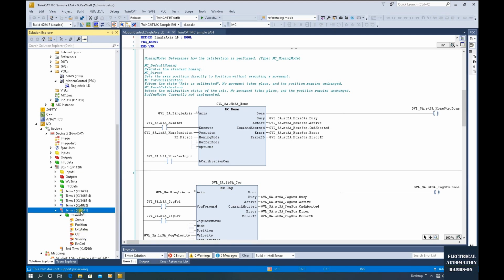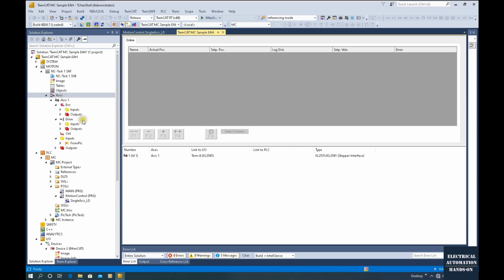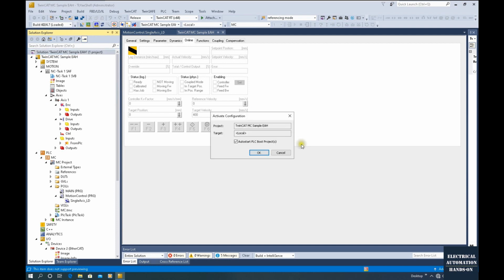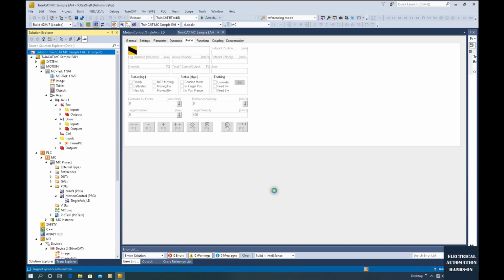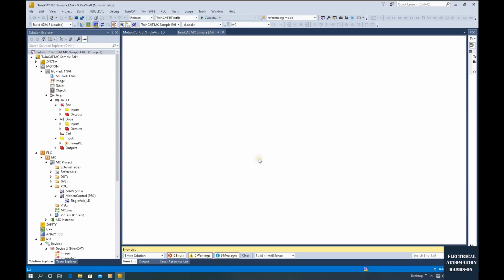And we tested the hardware connection. We set up the axis and set up the parameters. Don't forget, after we set up the axis, we download the hardware and then switch to online. For example, now I click download to download all the hardware configuration and switch the system to run mode. We haven't downloaded the program yet. This is only the hardware portion.